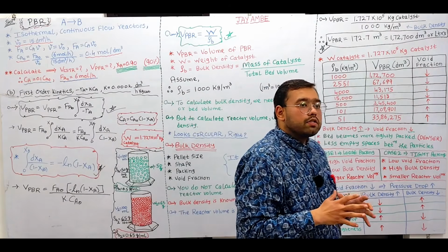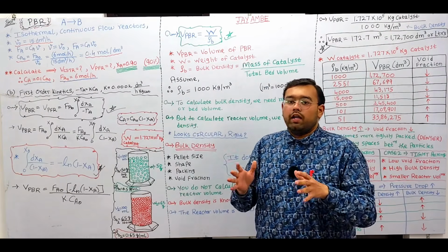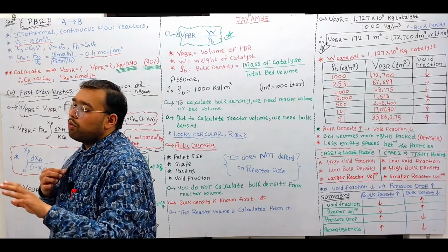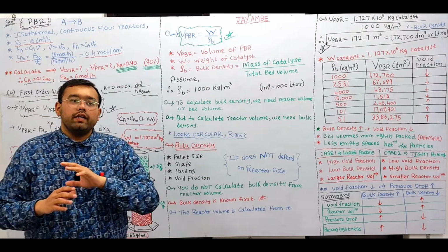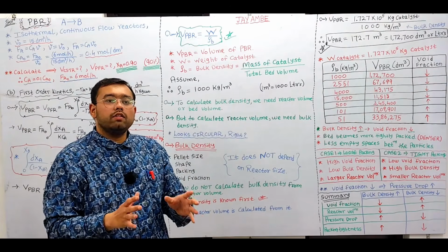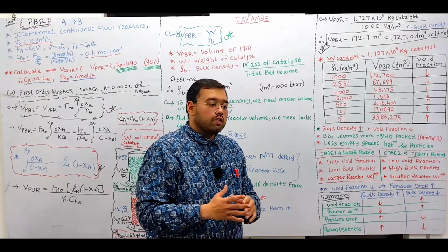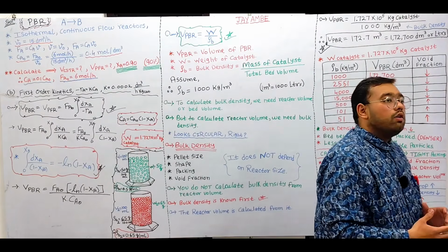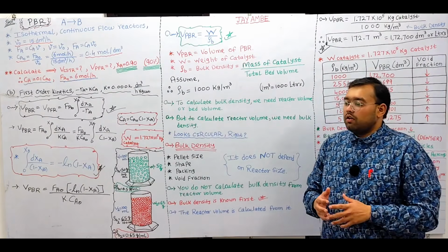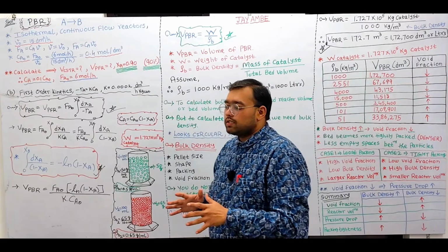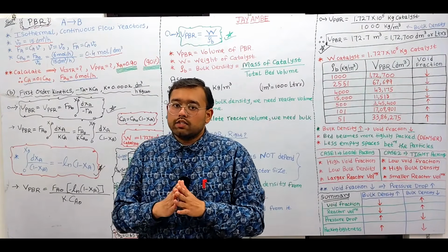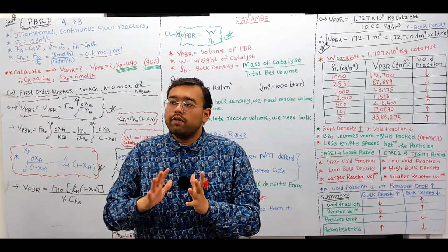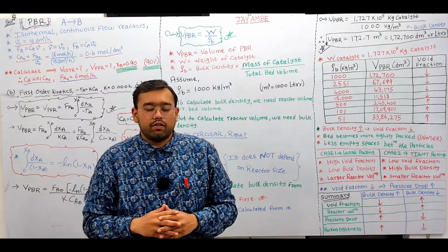The principal difference is that in the Packed Bed Reactor, the hollow space of the tubular reactor is entirely filled by solid packing. The solid packing can be a solid support, inert materials, or solid catalyst. Due to those reasons, the Packed Bed Reactor differs from the plug flow reactor.